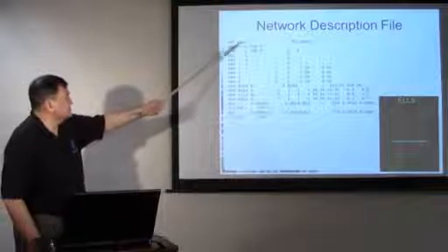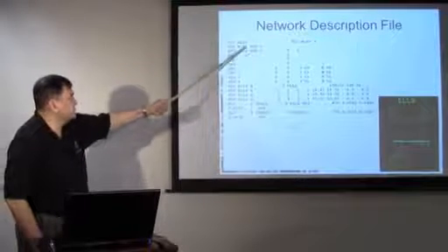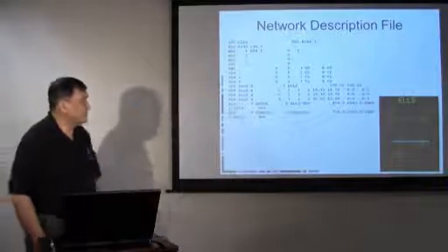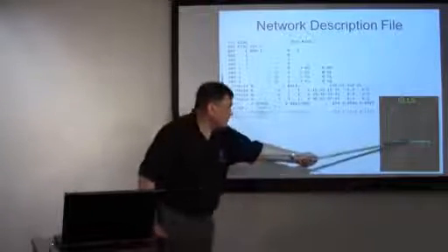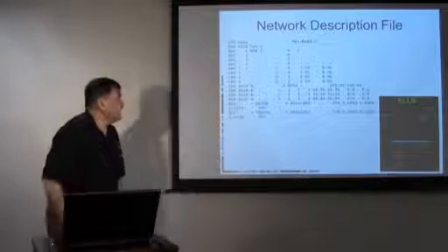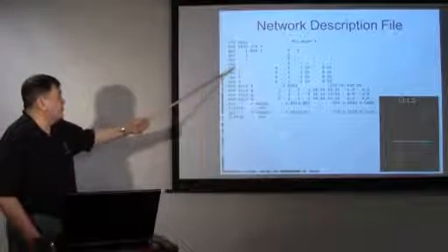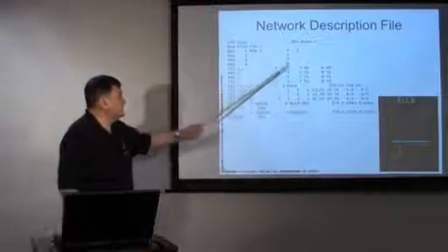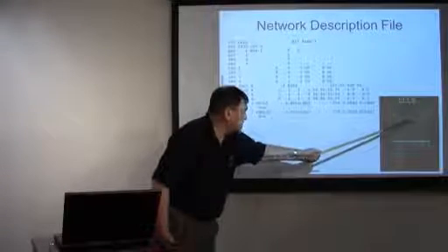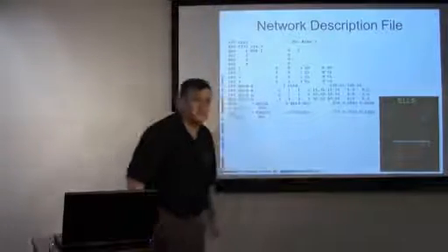So we have the station ELS, we have the voltage level at 230, and then we have these nodes, 1, 2, 3, 4. Here are the nodes, 1, 2, 3, and 4. And we define the connectivity for breaker 1 as going from node 2 to node 3. We see here, breaker 1 is going from node 2 to node 3.